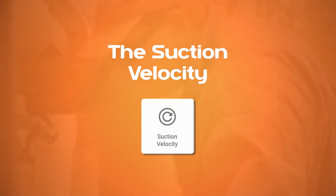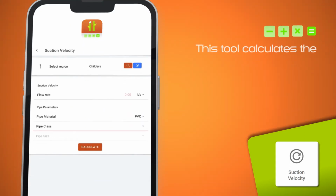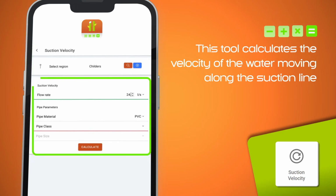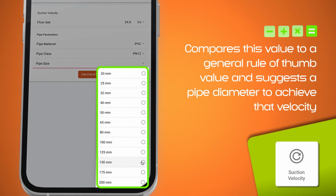The suction velocity. Many issues in centrifugal pumps arise from problems with the suction line. The suction velocity tool calculates the velocity of the water moving along the suction line. It then compares this value to a general rule of thumb and suggests a pipe diameter to achieve that velocity.